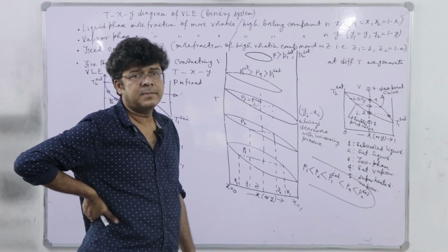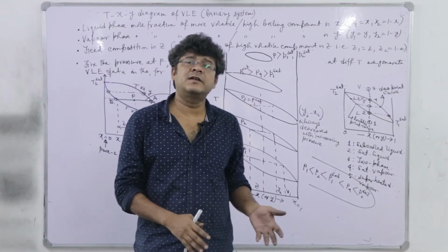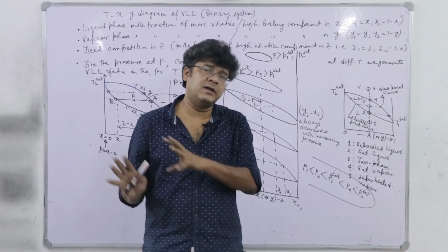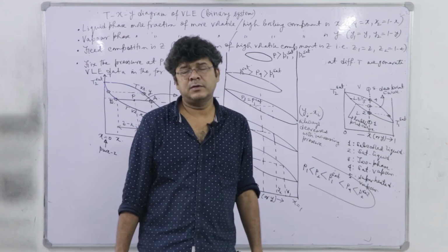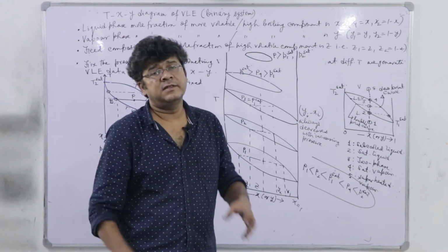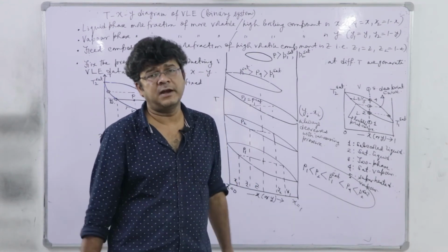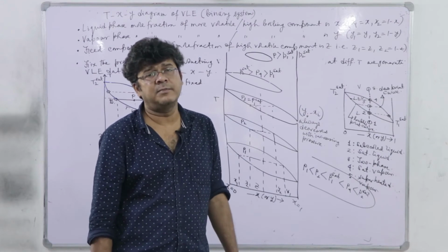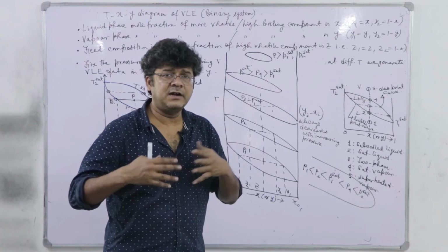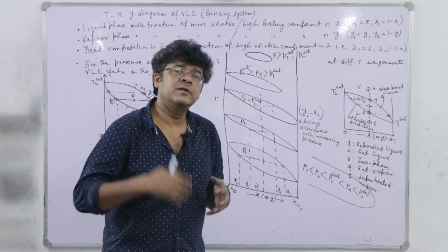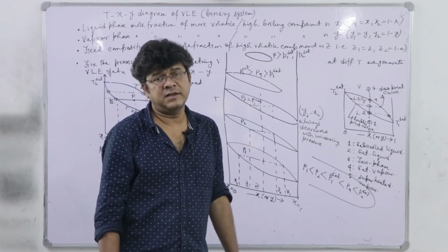Okay. So we should always conduct a distillation, preferably, if we do not think of economy, at lower and lower pressure. And that is why, when we fail to separate the components from a multi-component mixture such as petroleum at atmospheric pressure, we jump to vacuum distillation units.